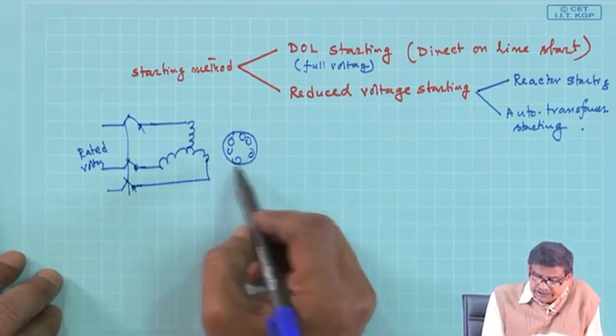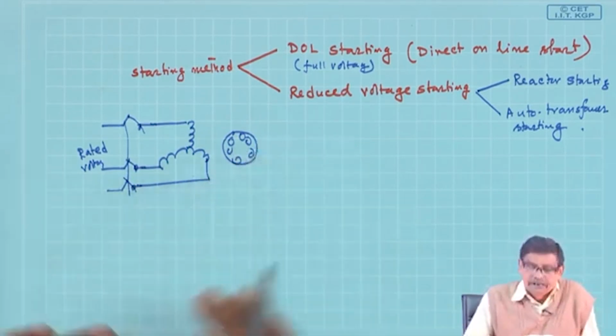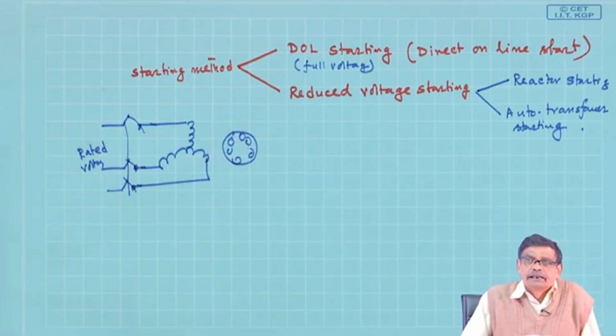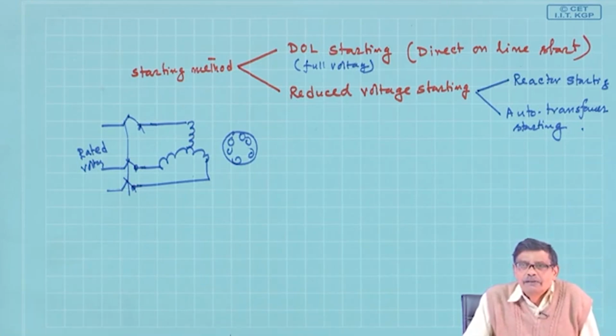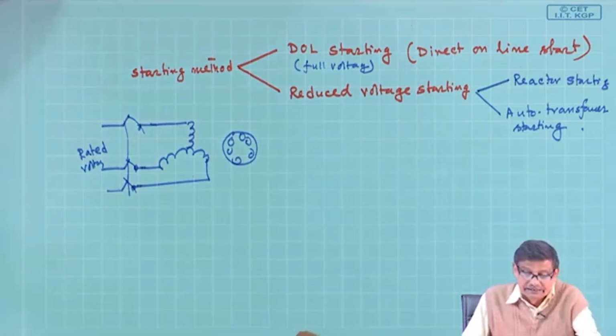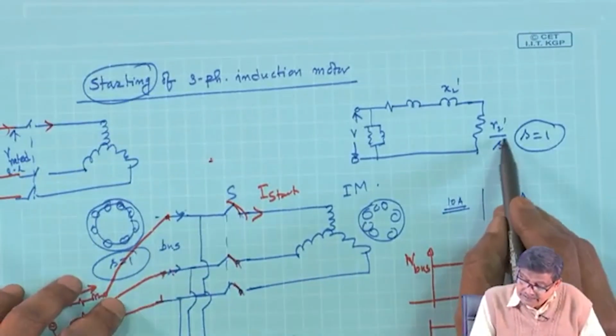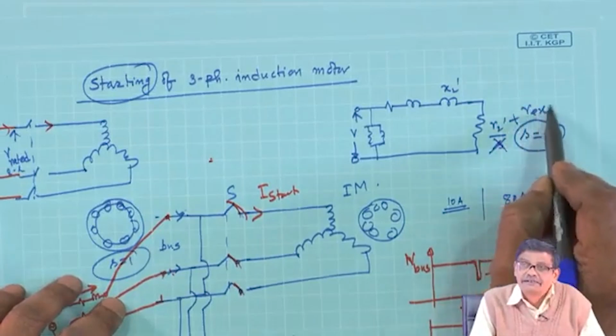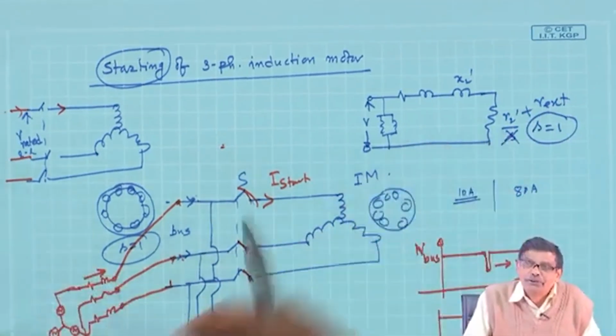Acha, you see I am drawing always, just the last word in this lecture, cage rotor I am telling. In case of wound rotor, the problem is less severe in the sense that rotor terminals are available, and to limit the starting current I will connect external resistance R2 per phase, and this will not only increase the resistance R2 plus R external, but at the same time it will also improve starting torque.